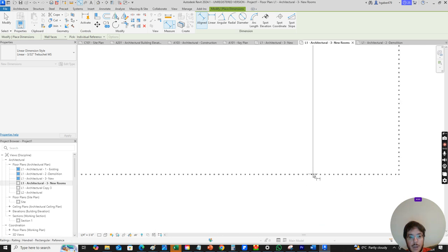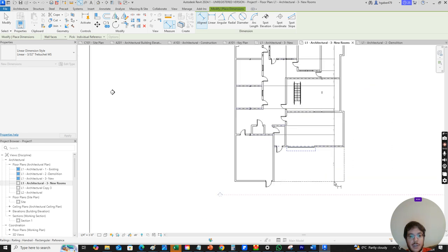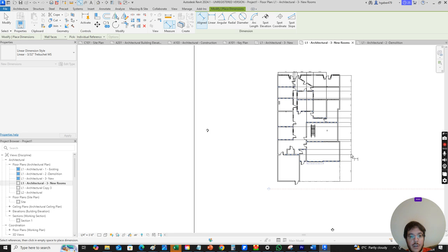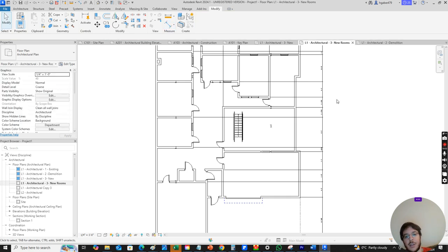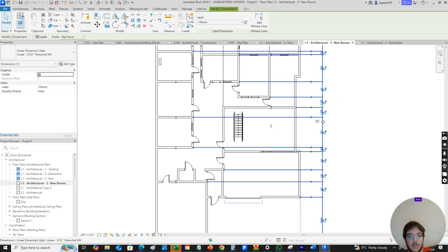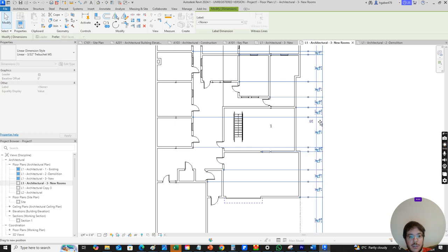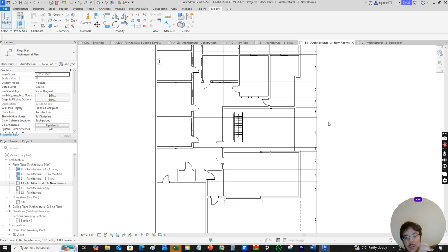Now here I've got an outdoor railing which doesn't like to snap, but I can be pretty close here. So now I can put these. Now if you don't like the distance, then you can press Escape, and now you've got your measurements. You can move these really easily, see? They're quite easy to move, and then these end up on your drawing.